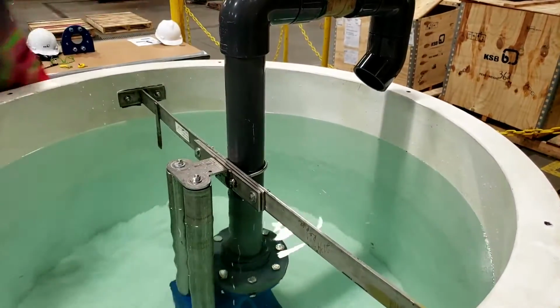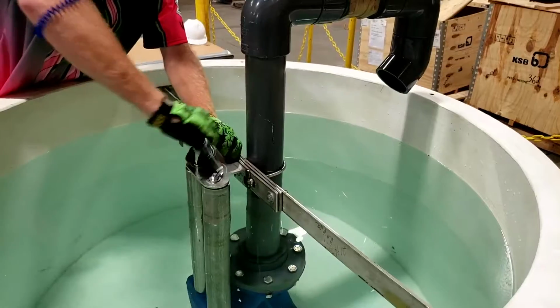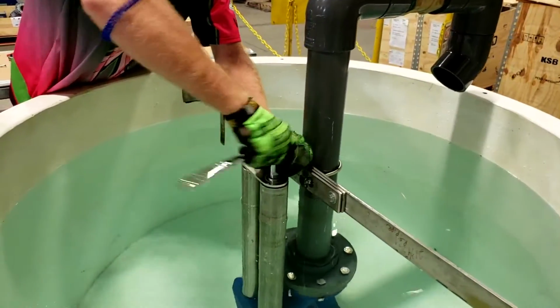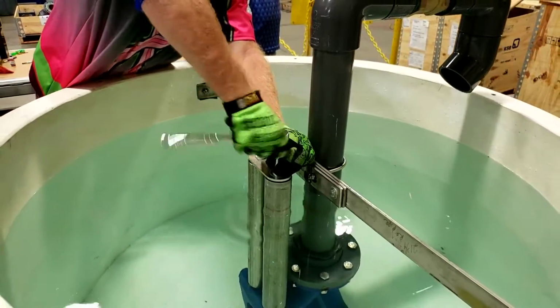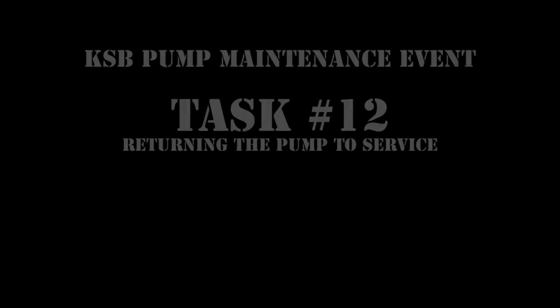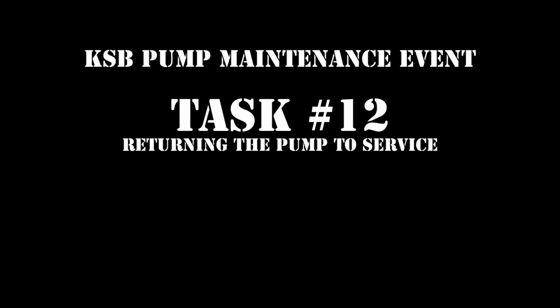Install the old 9/16 inch nuts on the guide rail bushings. Nuts must be installed so that they are at least flush with the stud or bolt. KSB Pump Maintenance Event Task 12, Returning the pump to service.